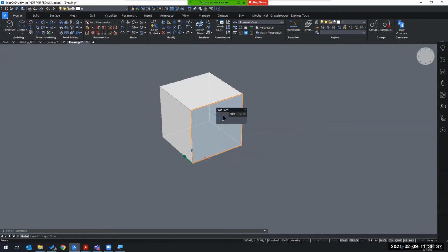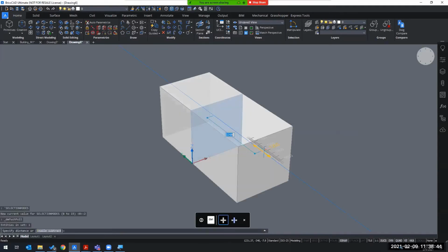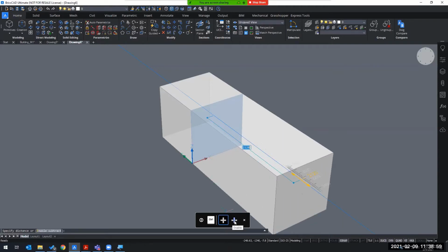As you can see, the quad already recognizes what I most likely would do. And just in case, there are some extra suggestions for the face, but I'm just going to do the push-pull. This is something really important to keep in mind. When you're using push-pull, as you can see on the tips here at the bottom, I can either keep this continuous as a union, or it is going to subtract on whichever entity will intersect.